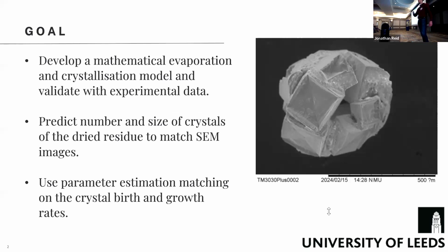But at the same time, I've been working also on a crystallization model, and my goal there was to try to be able to predict the number and size of the crystals from the dry residue of the saline droplet at the end of evaporation, and see if we could compare this with SEM images. Now, for that, I've used parameter estimation matching on the crystal birth and growth rates from the crystallization model.